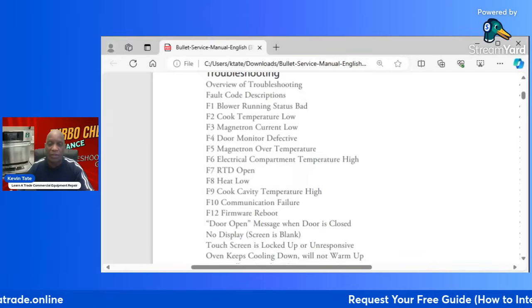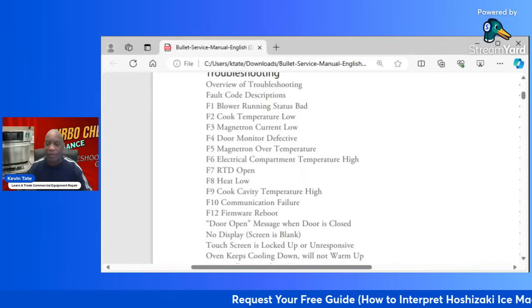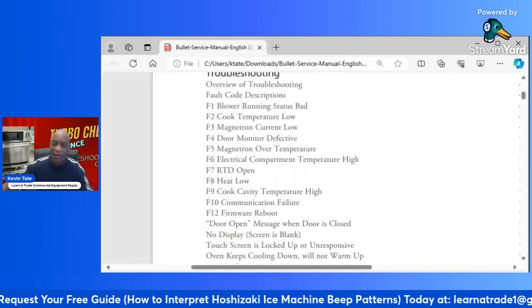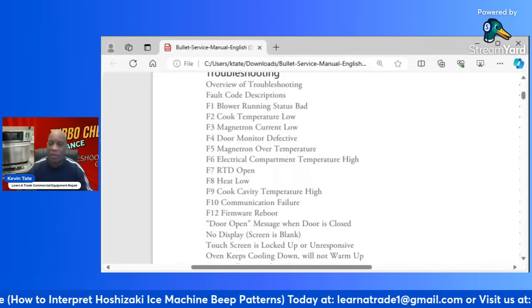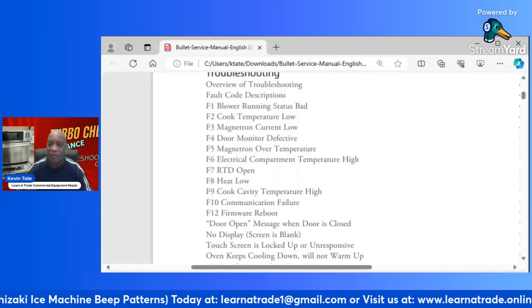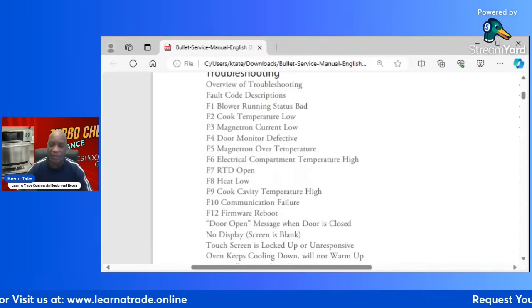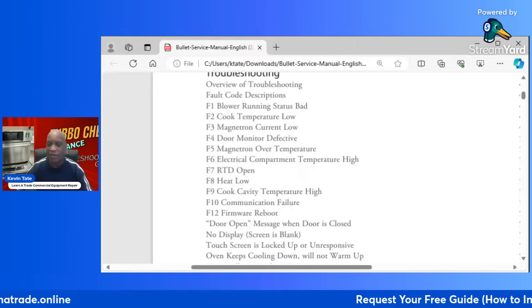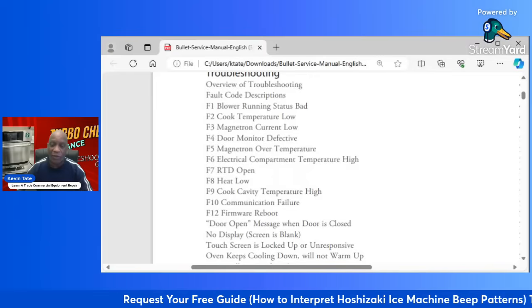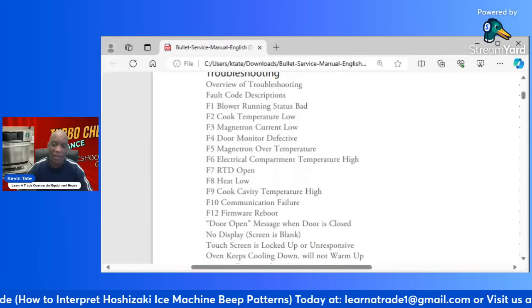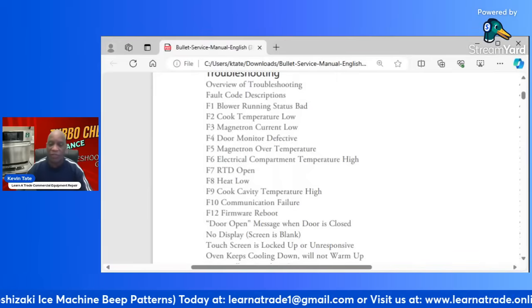You need to remove it anyway so that you can make sure that your waveguide is not contaminated, because if there's any grease inside of that waveguide, that's going to be part of the issue that the F3 error is coming up for. So you definitely want to go through that and make sure that magnetron is good to go. If you have any questions in your mind about it, the best thing to do is go ahead and change the magnetron, especially if you had a bad transformer on that side. Okay, so you want to check that on both sides also.